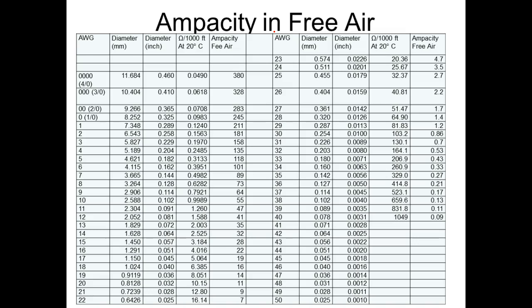So when the National Electrical Code came out and they said you use 14 gauge wires, are they going to rate it at 32? No, because they're all going to be insulated. They're all going to be ran in walls. They're all going to be ran all the way from the equator all the way up to Alaska. So one thing they wanted to do is they wanted to rate it at an ampacity where you could run it through the ceiling of your house in Alabama during the summertime and still say it was rated, it could handle this much current. Anybody know what NEC rates a 14 gauge wire?